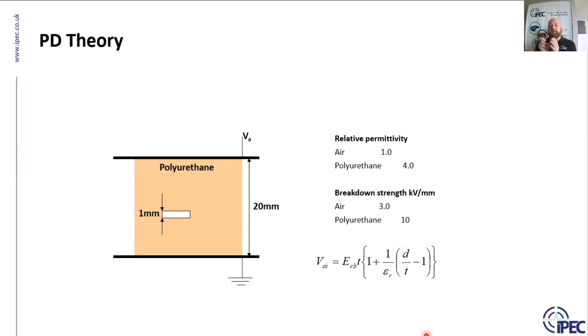However, the problem is that in our defect here you've got some XLPE, then a gas-filled void or an air gap, and then more XLPE. What that means is instead of a uniform dissipation of the energy from the conductor, you get a localized area of capacitance, a localized area of stress. So as the energy in the power cycle increases, the stress very specifically at that defect point increases also. And as that stress increases within normal working voltages, you will get a very small low energy breakdown across that defect. So it must be noted that breakdown is at the defect.